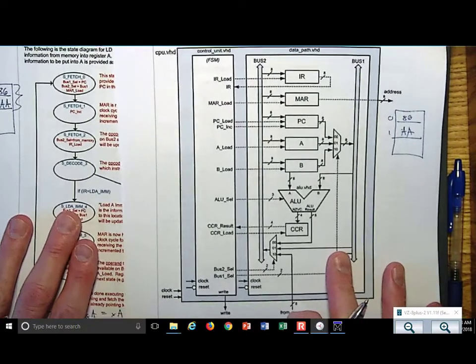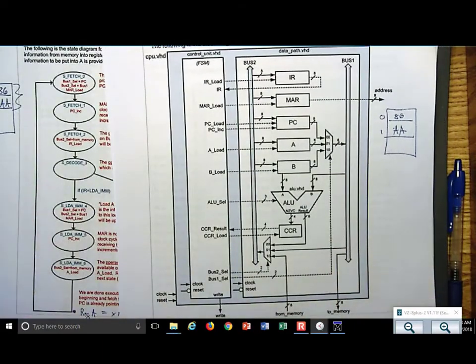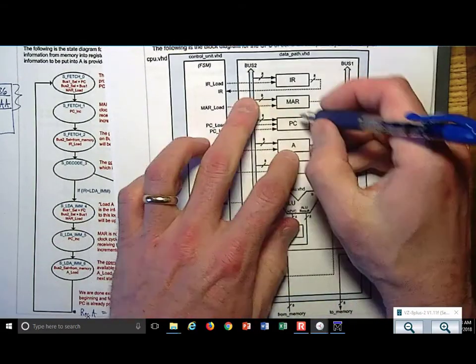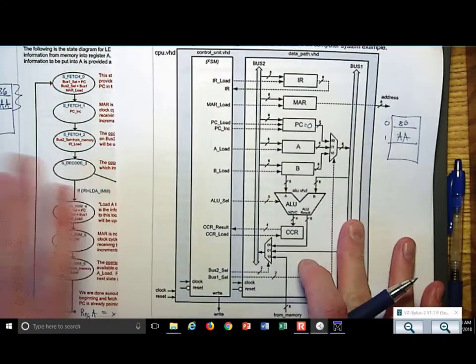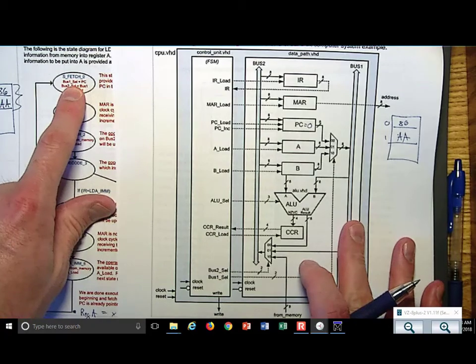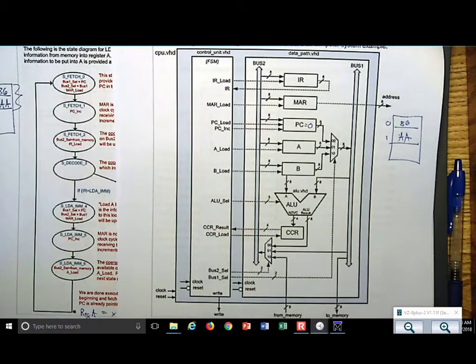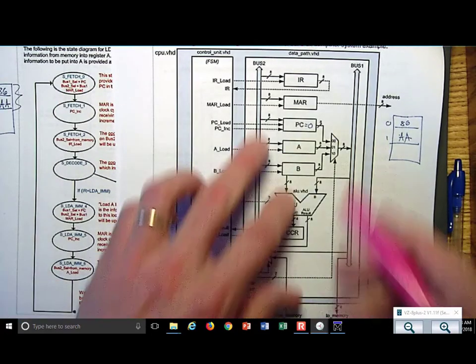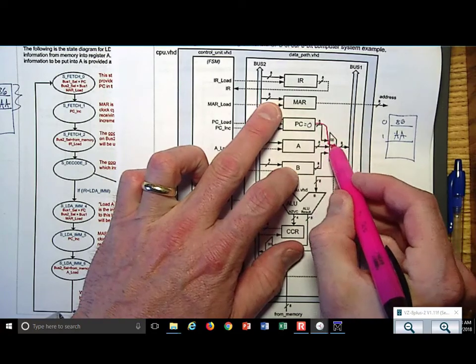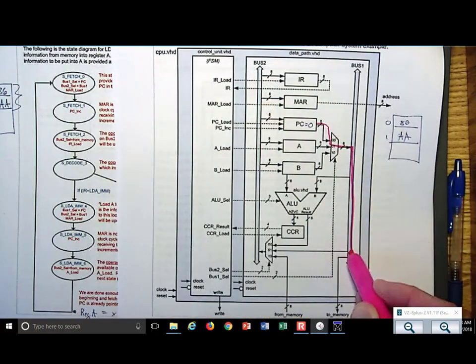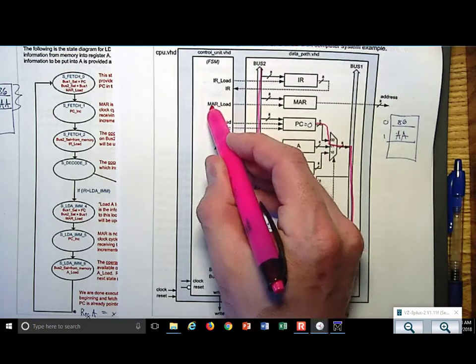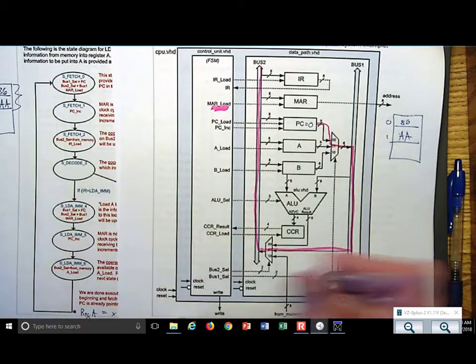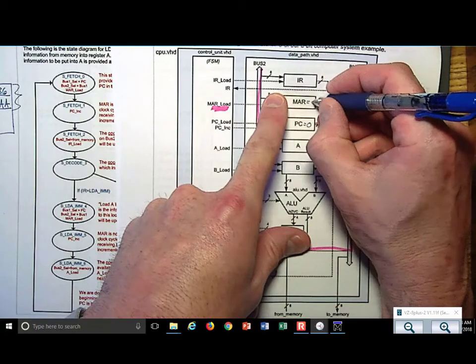even better. When I said go, that meant program counter gets a 0, and I want to start executing. I change my buses, bus 1 select and bus 2 select, in order to get 0 through this multiplexer onto bus 1, over through this multiplexer onto bus 2, and then I did a MAR load. The next state I see that MAR got 0.